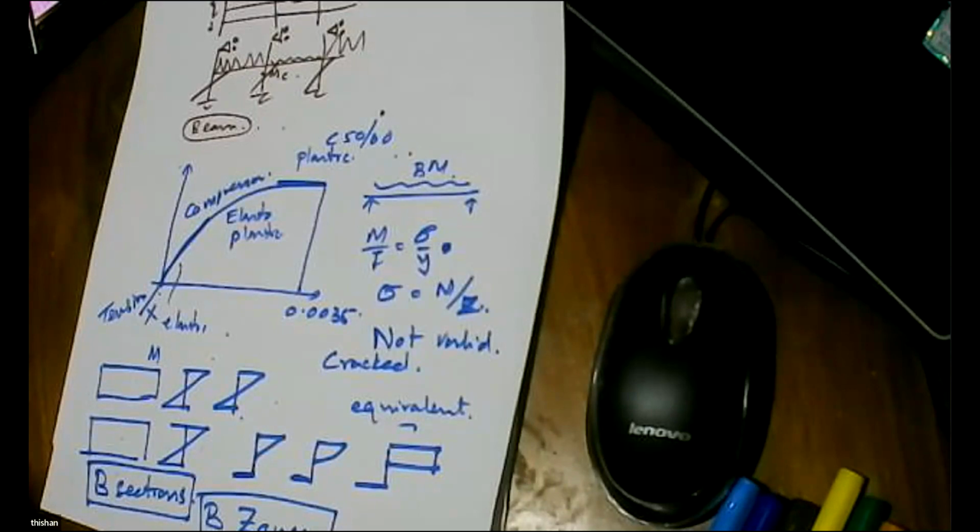That is the general rule. So if it is a 600 millimeter pile, you will socket 1 meter. If it is a 1200 pile, you will socket 1200. If it is a 1500 pile, you will socket 1500 millimeters.